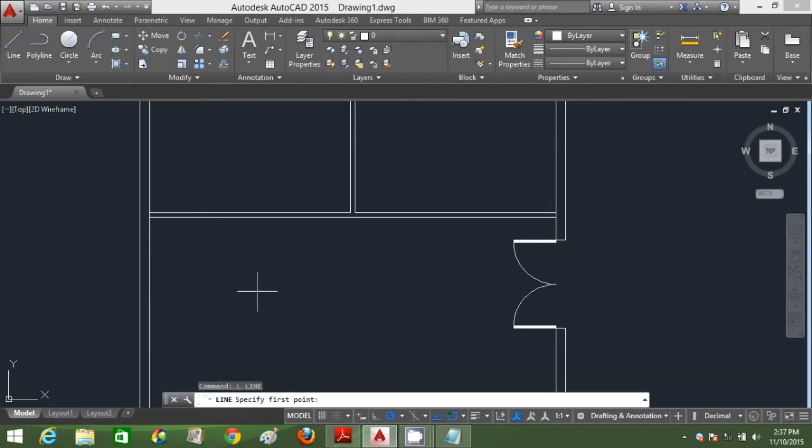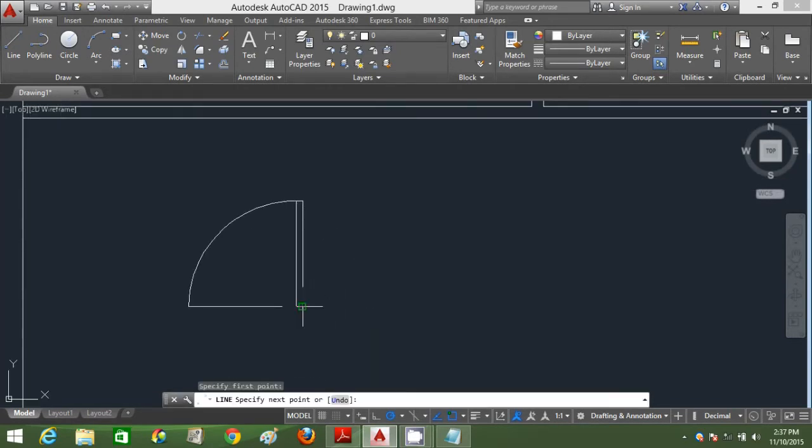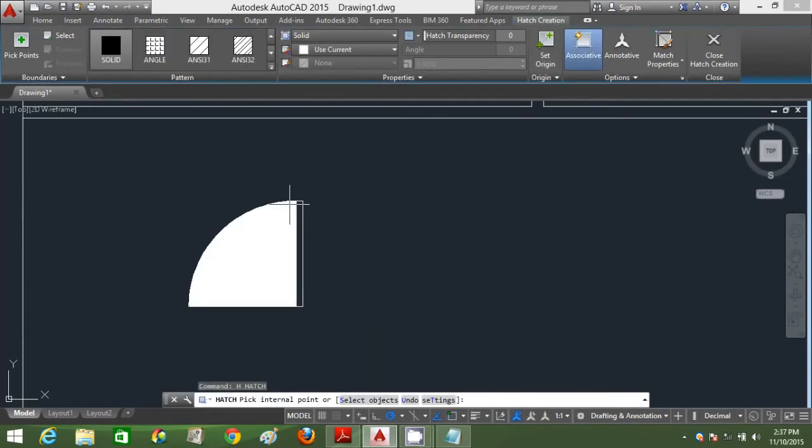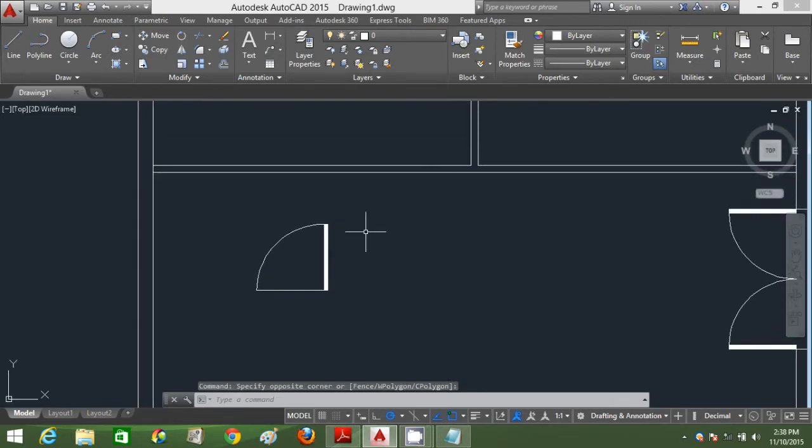Okay. Press L, enter. Right. I'm just trying to draw another door here to actually set the door for the executive office. Okay, so I got the door ready already. So I'm gonna offset it by 50 mm. Select that particular portion and offset it out. Close this portion, close that part. Okay, hatch it by using solid pattern. Hatch the door. Okay, I got that part already set.